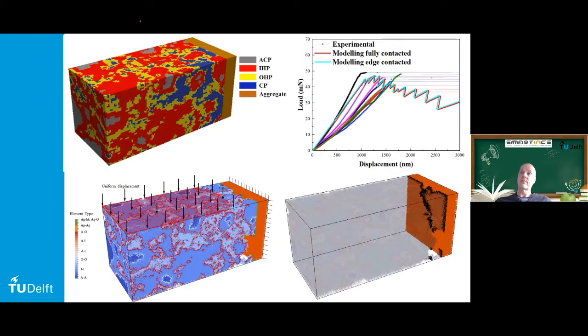So that's why it will fail much more easily here at the interface. So if we do the same in the model, we model the aggregate. This is our cement-based prism sticking out. So we load it here, and we can then choose some value for the interface element, because all these elements, we know the strength, we know the stiffness, but the connection between these two, that we don't know. And we can just fit it back in such a way that we have the same results for the experimental tests, which are all these lines here, and the simulation. So this is the simulation, where we again can also have the post-peak regime. So we just fit them back by inverse modeling, what the local interface properties should be, so that we get the same strength values here. And then we have the interface properties.